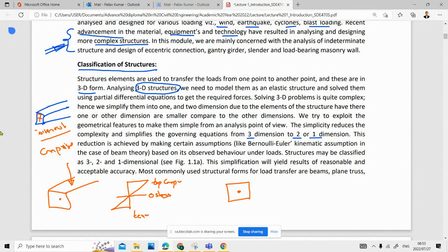No, Ethan. It's a direct stress. If you try, it will be the shape of that stress instead of triangular, because all parts will be in compression. It will be straight away like this. This is P by A, straight away force over area, and that will give you a direct compressive stress. And this is a part of your bending stress. The one which we have drawn is part of bending stresses, right?